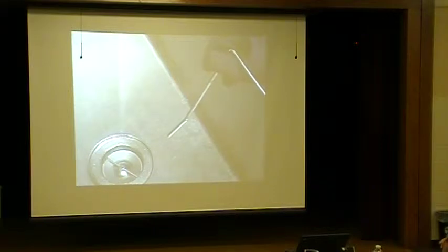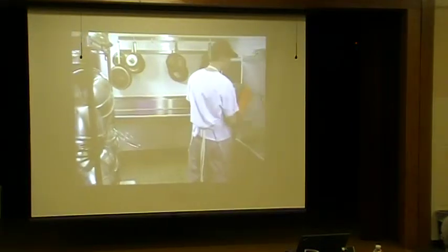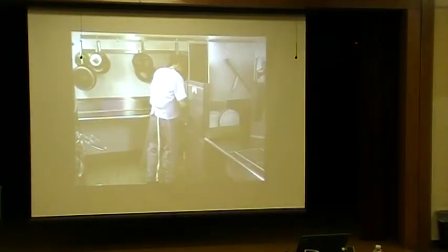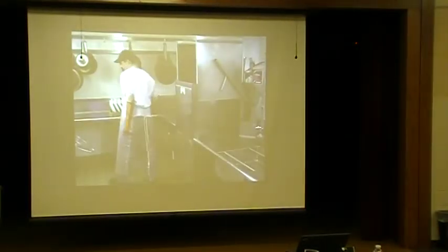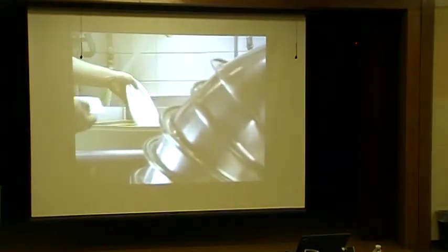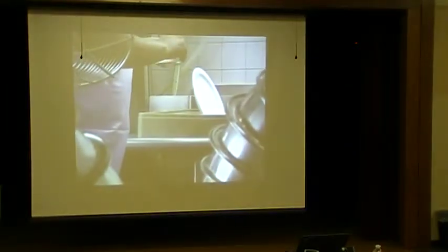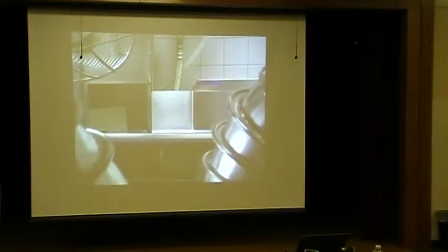It might also be necessary to install a heating device to maintain this temperature. The other heat sanitizing method is the high-temperature dishwashing machine. This uses hot water to sanitize tableware, utensils, and other items. To check the water temperature in these machines, attach temperature-sensitive labels or tape, or a high-temperature probe to items that will be run through the machine.